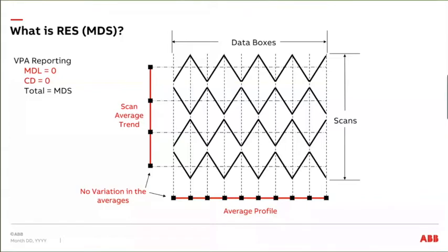From the back of the machine to the front of the machine, I'd say, okay, your problem is in moisture, machine direction, we're going to do bump tests, and we're going to fix this. And it is remarkable how fast you can look like you know what you're doing if you can interpret this data. And that's what we really wanted to convey here, is there are ways to do that.